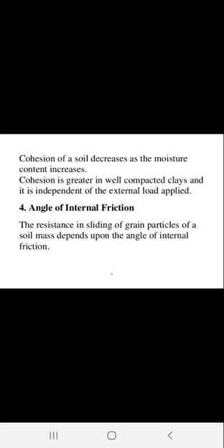So cohesion of a soil decreases as the moisture content increases, and cohesion is greater in well compacted clays, and it is independent of the external load applied. So whenever the soil or clay is highly compacted, the cohesion is maximum in that soil.